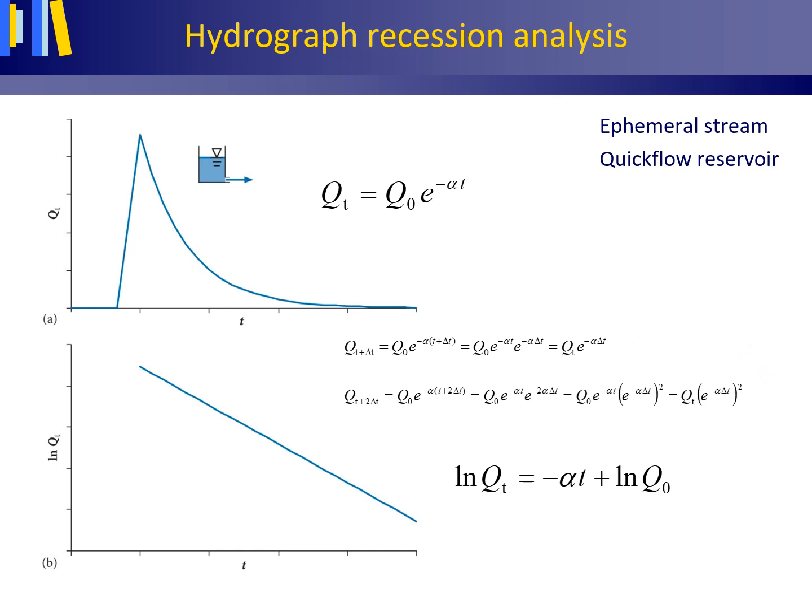and here. Remarks made for the decay constant alpha when introducing the Horton equation for ponded infiltration similarly hold for the recession constant alpha in these equations. E to the power minus alpha delta t is smaller than 1. Also, if the recession constant alpha is large, the recession curve shows a steep decline and the depletion of the reservoir is fast. Consequently, if alpha is small, the recession curve shows a slight decline and the depletion of the reservoir is slow. Alpha ranges from 1,000th per day for deep groundwater to over 3 per day for overland flow.